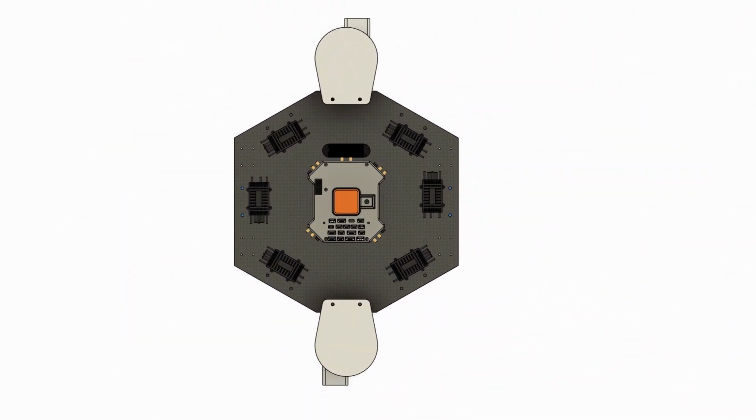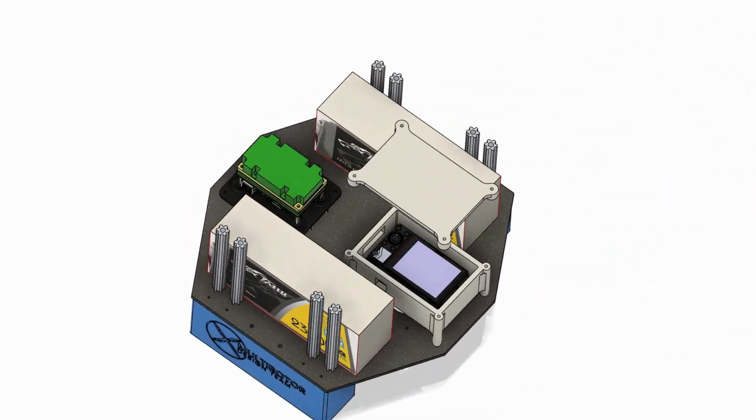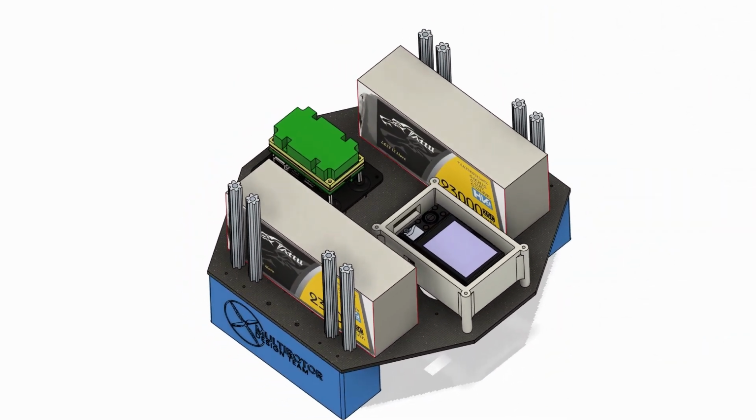As you go down, we have our autopilot, which connects to all of its ESCs, which go out to the motors, as well as our ExpressLRS to give us the remote connection, and our servo connections on this layer. On our bottom layer, we house our batteries, our flight computer, as well as our camera to take pictures of the ground and the ODLCs.